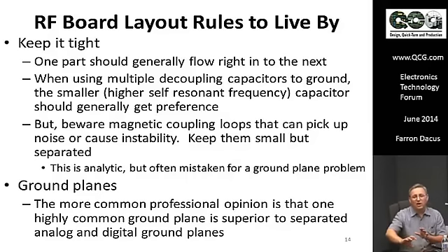So you might be surprised that, for example, you have a switching power supply, and you bring it near some sensitive circuitry. Then you put a linear regulator. And on the other side of that linear regulator, you have your sensitive circuitry. So there is a loop parallel to the ground plane where current flows, a current loop. And then over on the output side of the linear, there's another current loop.